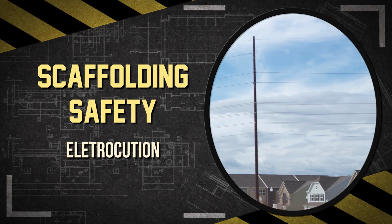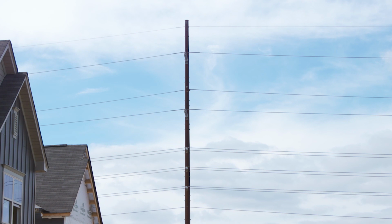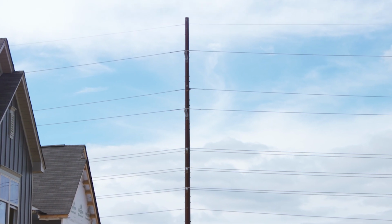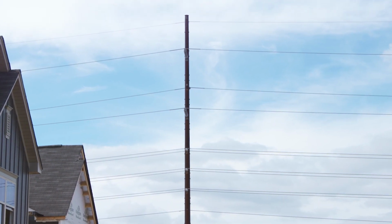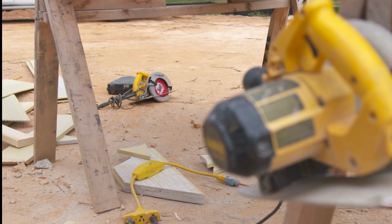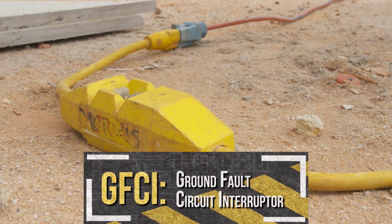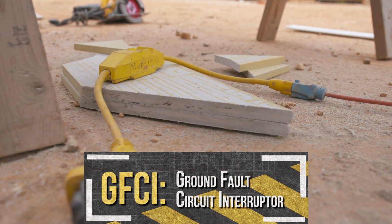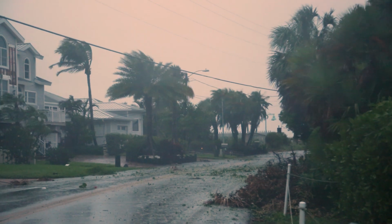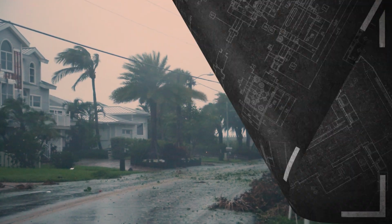Overhead power lines can be extremely dangerous, even deadly. Scaffolding should be built at least 10 feet away from an exposed power source, unless it has been insulated or de-energized. All electrical tools and power cords must be in good condition and protected by a ground fault circuit interrupter device, or GFCI. Do not work on scaffolds during electrical storms or high winds.